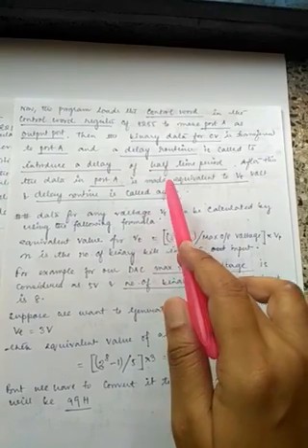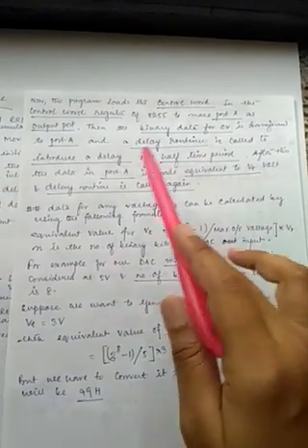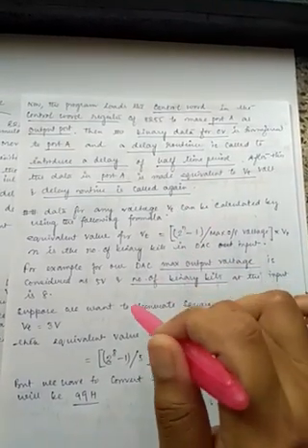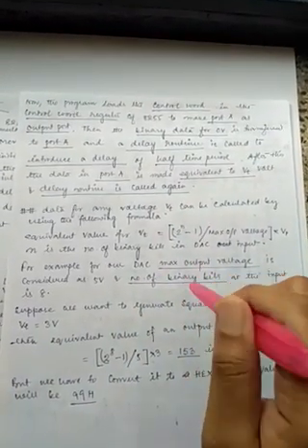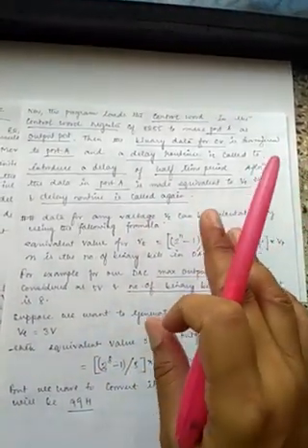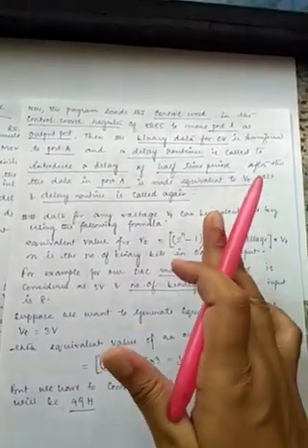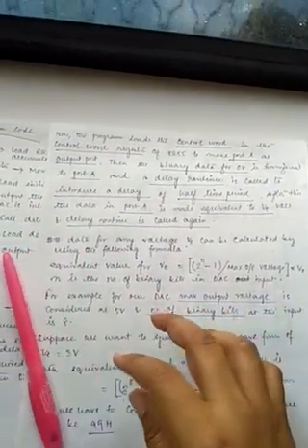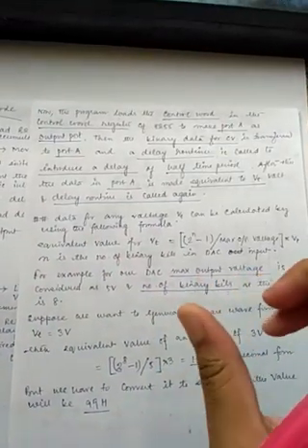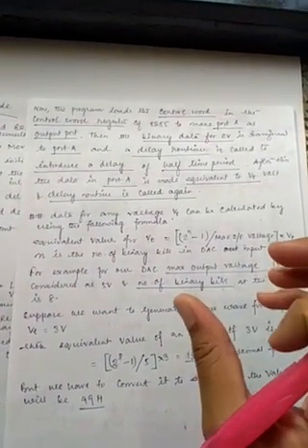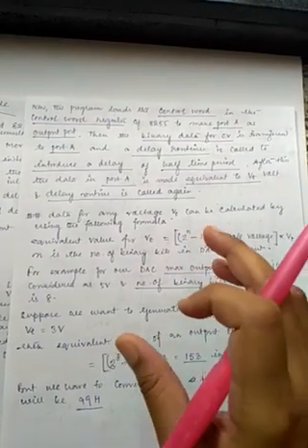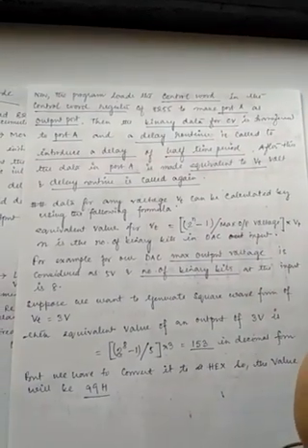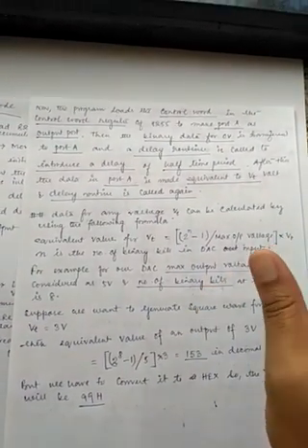Okay, so then the binary data for 0 volt is transferred to port A. Here is the confusion. This binary data, once we are using 0, once we are using Vt, but Vt may be the value of 2, 3, 5, anything according to your choice, but these values will be loaded in your port A. But there is one more constraint, that there is a half time period, because all the values are considered for half time period. The Vt is considered for half time period, means T by 2, and 0 is considered for another half time period, that is T by 2, and the total time period is T, right?